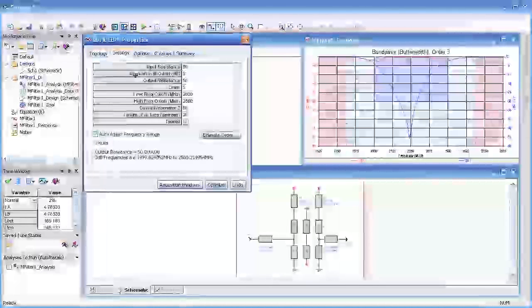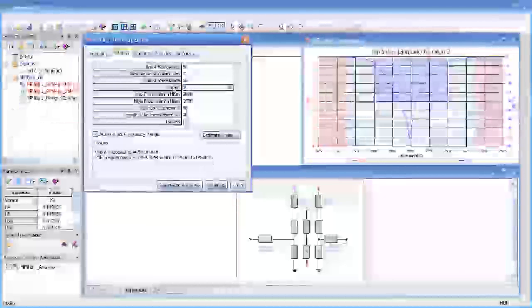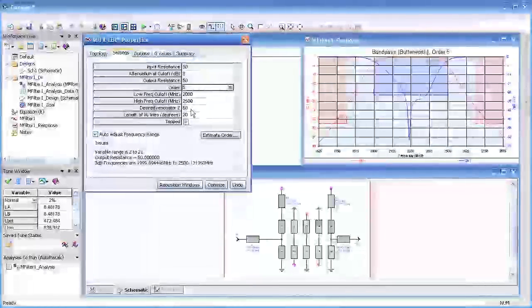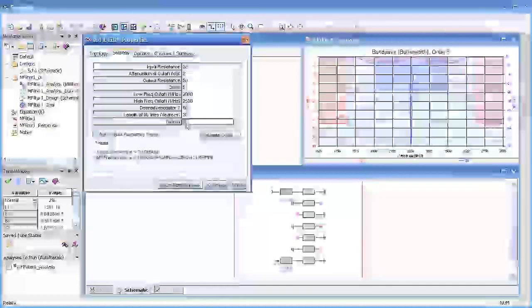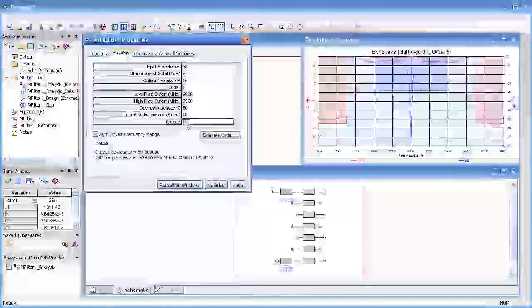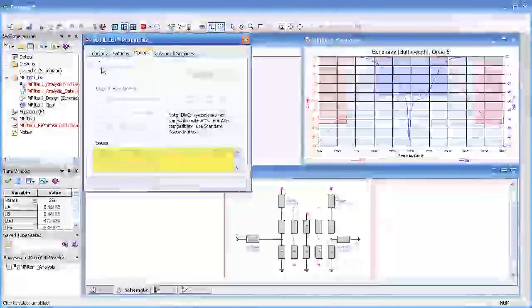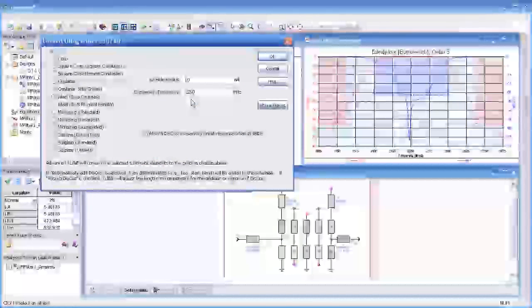And you see it immediately appears as well as the graph. I'll go to the settings, and I'm going to set the order of our filter to 5, and I'm going to accept the default bandpass characteristics. That's 2 to 2.5 gigahertz, and I'll also accept the default resonator impedance. You see when I deselect tap, we now have coupled end on our filter as opposed to tap. Tap works out better when you have broadband filters. We'll create a layout in the options tab, and then we're going to set the manufacturing process. That is how we realize this filter.